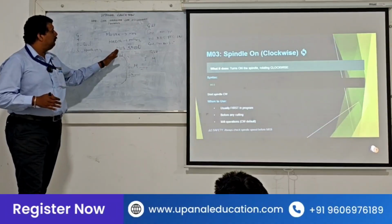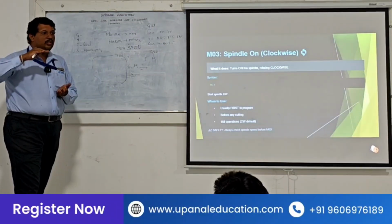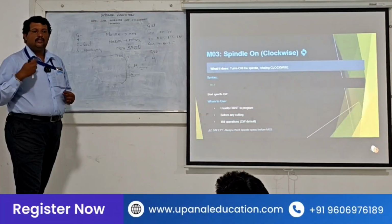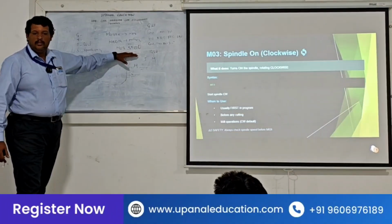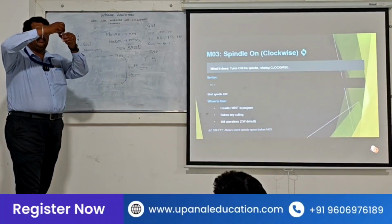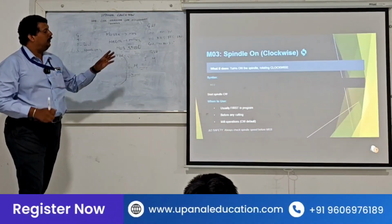We change M03 S to 2,000 or 5,000. We go in incremental speed, slowly increasing the speed of the spindle, because it has to work properly. At that time we give M03 S5000. There is no need for any work to be there. It is just rotating in the spindle. It's not moving or anything.